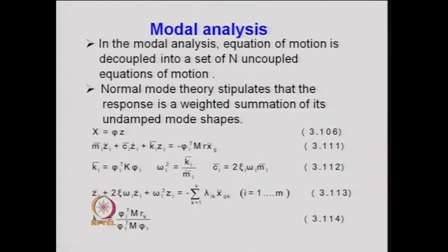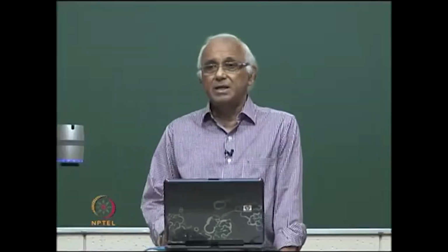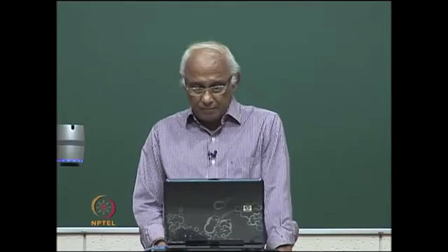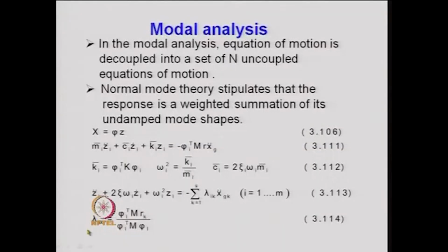That quantity is known as the mode participation factor, which has been discussed, I am sure, in your dynamic analysis class. So, for single point excitation you have the mode participation factor as a single quantity, but if it is a multi support excitation system, then there is not a single value of the mode participation factor. The mode participation factor then becomes support dependent. That means, for each support we have one mode participation factor defined.